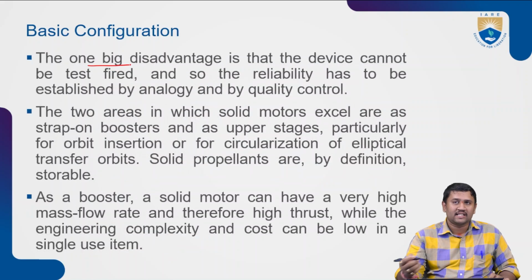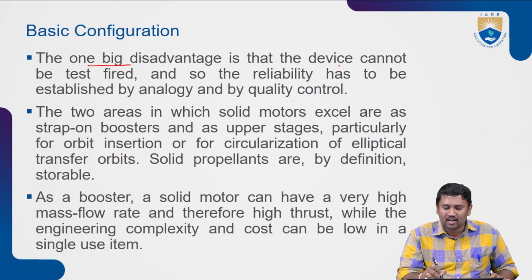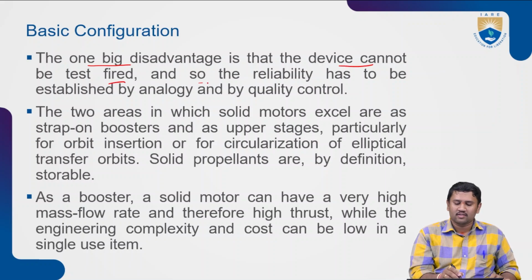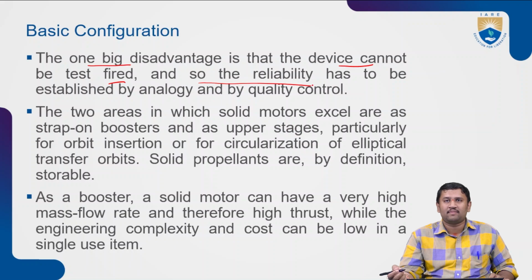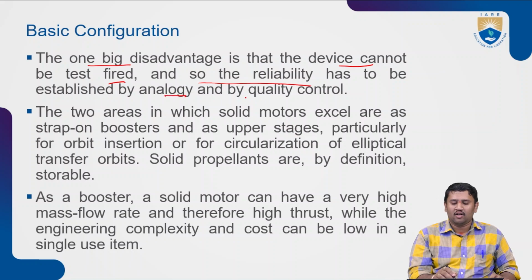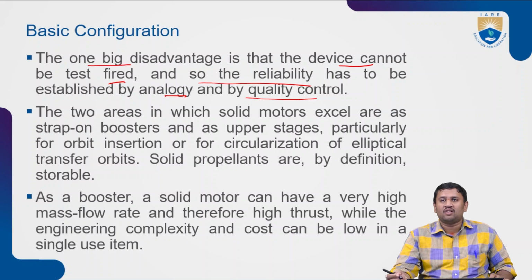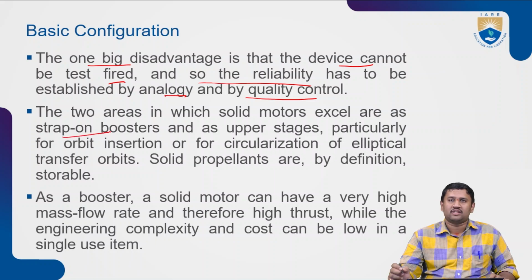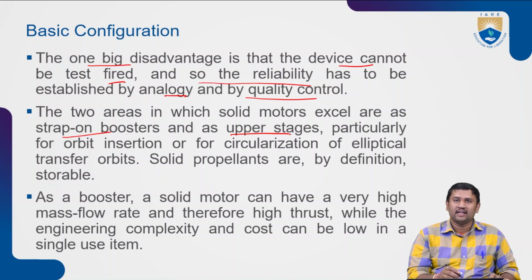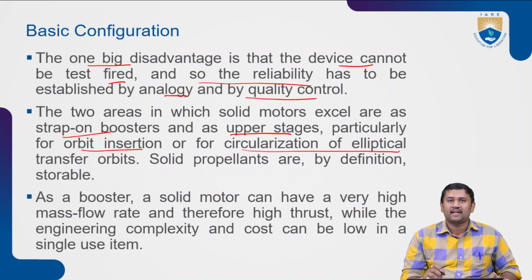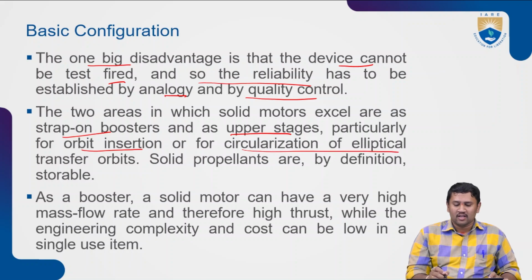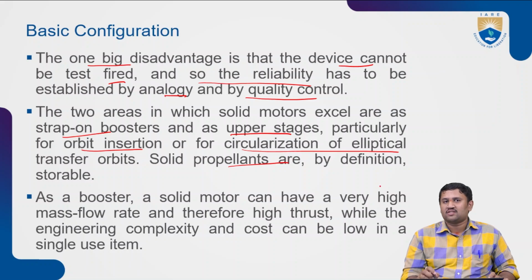The one very big disadvantage is that the device cannot be test fired, so the reliability has to be established by analogy or by quality control. There are two areas in which solid motors excel: as strap-on boosters and as upper stages, particularly for orbital insertion or for circularization of elliptical transfer orbits. Solid propellants are by definition storable.